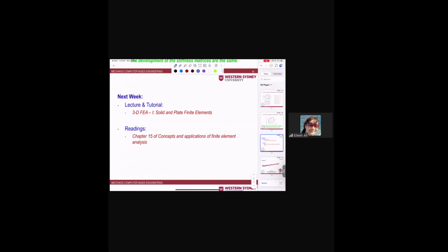That's all for the lecture today. And today we discussed the other 2D element, the rectangular element. To be honest, the 2D rectangular element is more commonly used than the triangle element. And it is a better element which can give us a more accurate solution, which means you can use fewer elements to solve the problem and get better results.